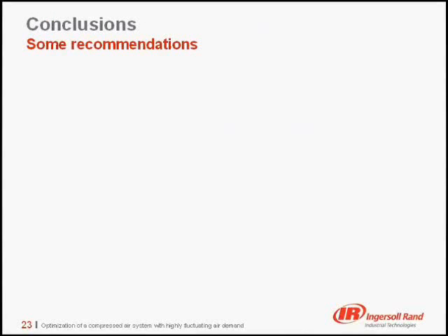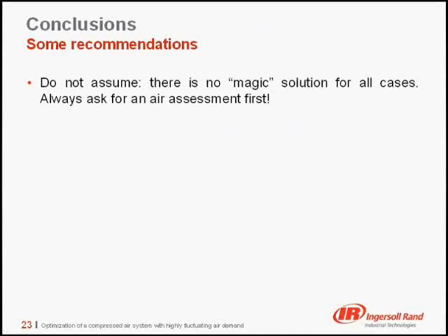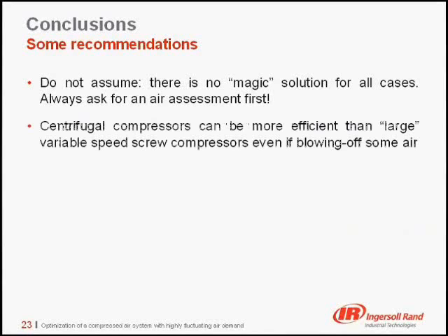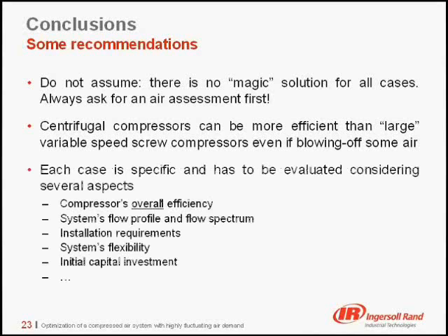So, in conclusion, some guidelines or recommendations. Never assume which is the best solution. There is no magic solution for all the cases. Always ask for an error assessment first, but make sure it is also read and interpreted in the correct way. Remember that centrifugal compressors can be more efficient than large variable speed screw compressors, even if they are blowing off some air. Each case is then customer specific and needs to be evaluated considering several aspects, the most important of